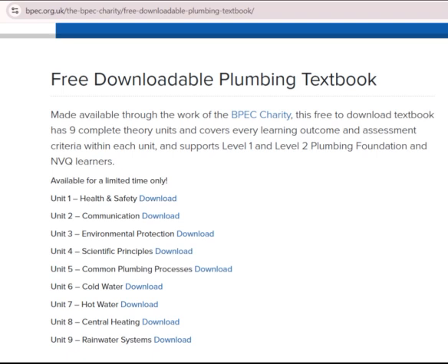Collar and tie on or off changes clothing by plus or minus 0.13, plus or minus 0.8°C. Seated or walking around varies metabolism by plus or minus 0.4, plus or minus 3.4°C. Stress level varies metabolism by plus or minus 0.3, plus or minus 2.6°C.